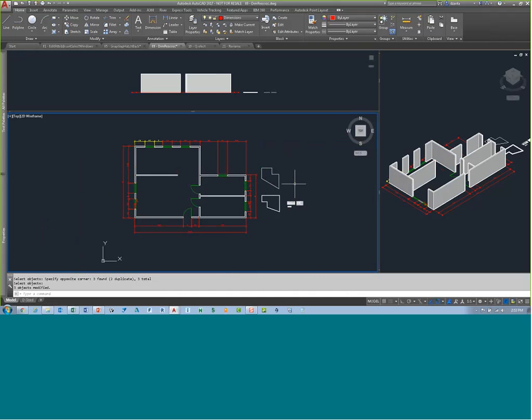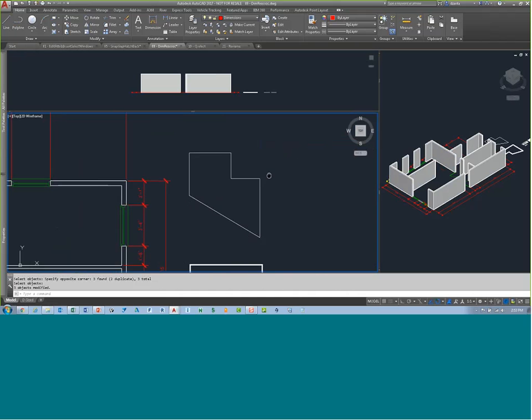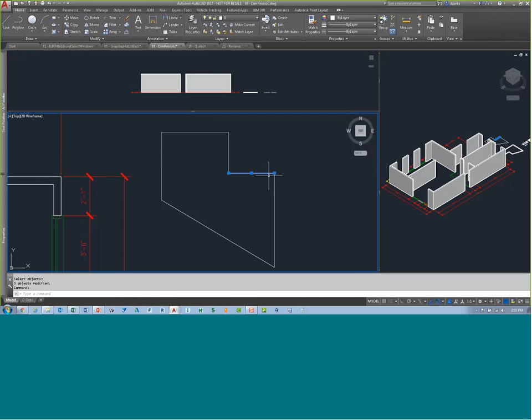Another tool tip is, when we have a whole bunch of lines that we've drawn from end to end, and we want to turn them into a polyline, we type in pedit, we select a line, and it asks us, do you want to turn it into one? This default is always turned on and always is yes, so you have to hit enter to accept, and then join, and then pick everything, and then hit enter, and enter again, and you're done, and now you have a P-line. That question that pops up gets to be very annoying for a lot of people.